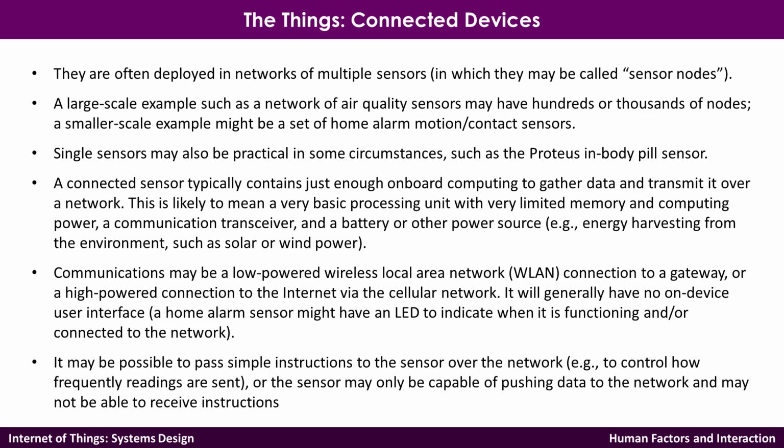However, we discussed earlier in a different lesson that network communication is not necessarily cheap in terms of the energy budget. It consumes a certain amount of energy, and an energy that is quite higher than complex computation activities. Therefore, you need to be careful when you are employing these connected sensors in your IoT application to think about when you are sending the data and how much data you need to send.